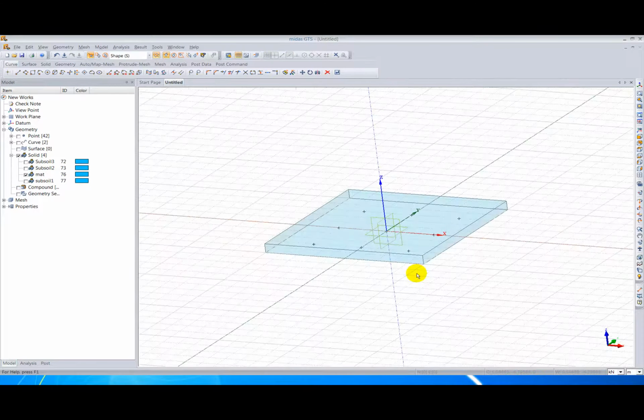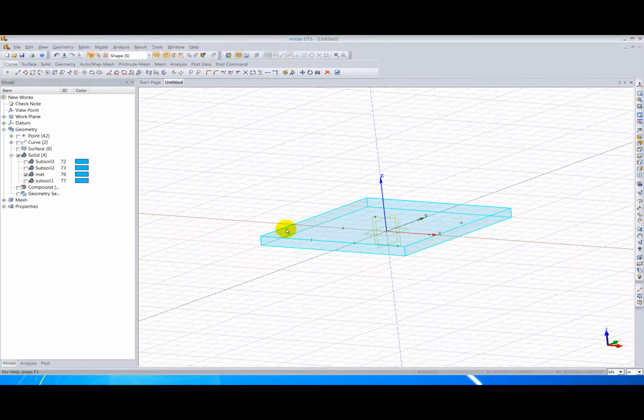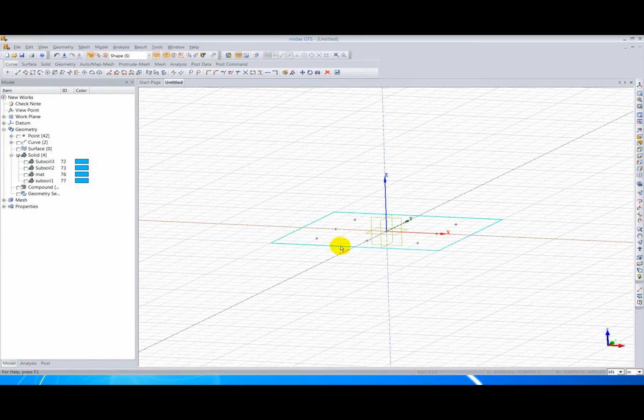So basically, here's the pile group design for this example. And what I want to do is first hide this mat and the wireframe, and I'm going to model the piles with a length of 27 meters and introduce a fixity which is going to be embedded into the mat with a length of 0.1 meter.